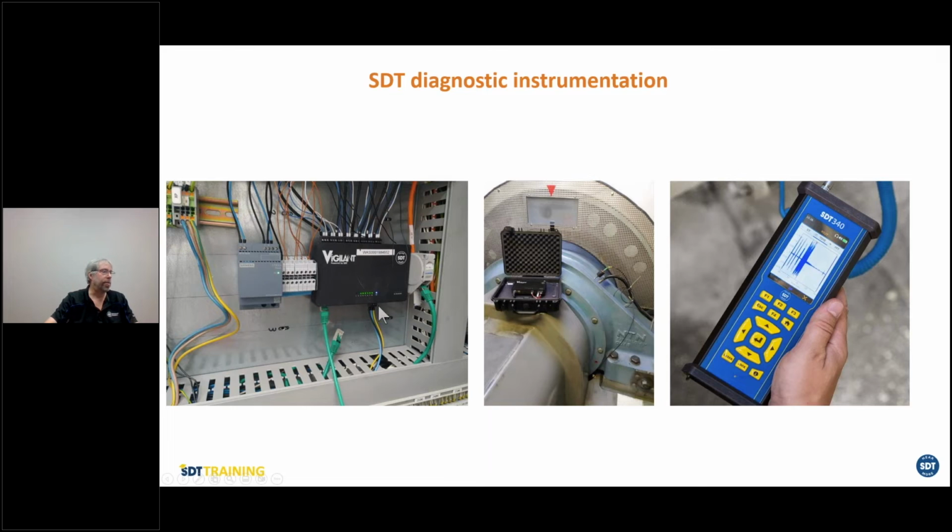The power supply goes in. You can also put a tach in here and other types of things like current draw, whatever you want. You can put some more inputs over here as well. I've written a little balancing program myself, and there's a phase analysis module in here, and I can actually balance with this thing as well, which is kind of neat. You have all your pickups going to your sensors, comes back, and it's all self-contained. The software is in there. You don't need anything else.